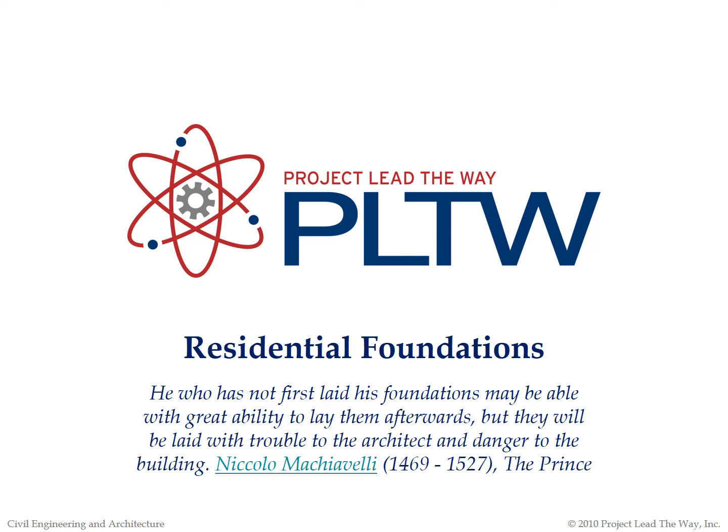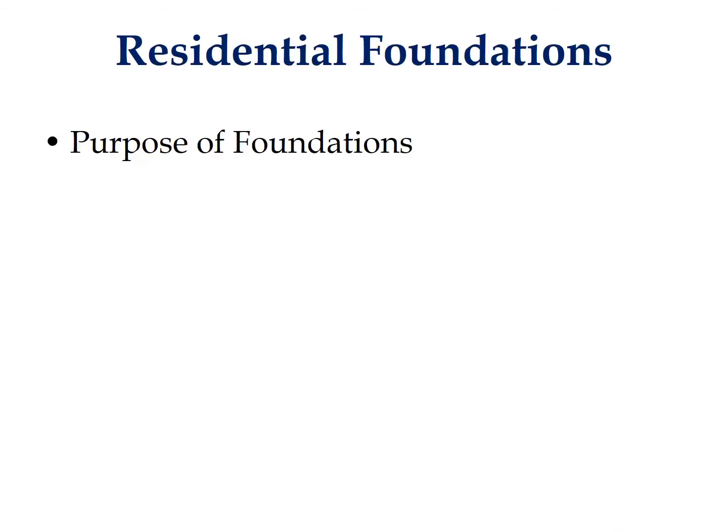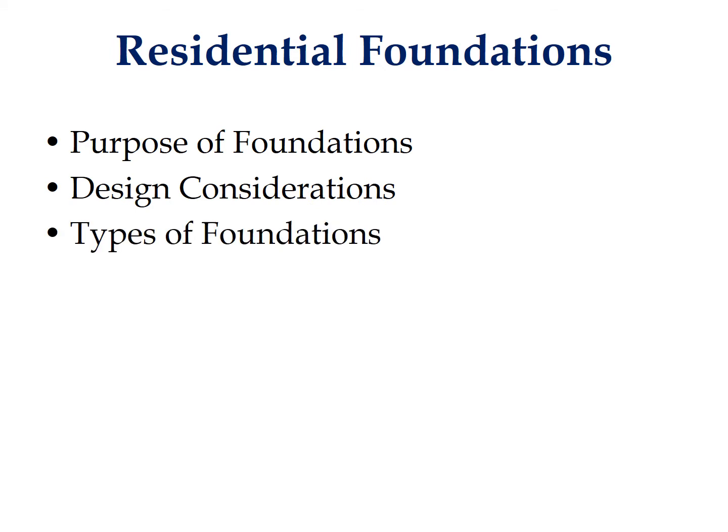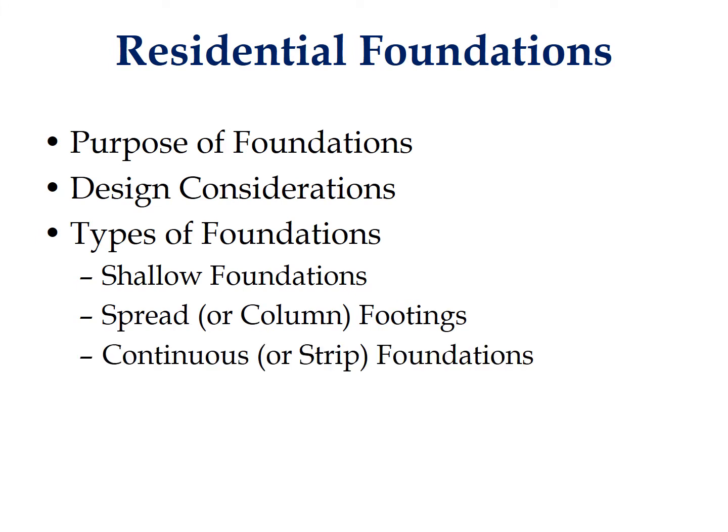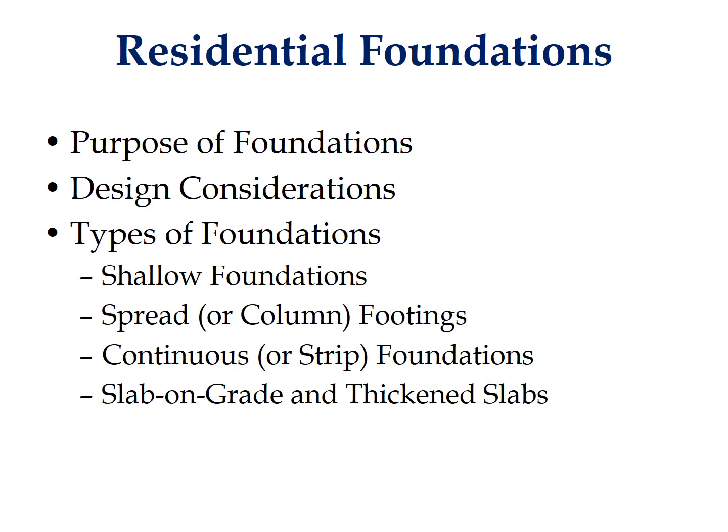In this presentation, we will talk about residential foundations. We're going to talk about the purpose of foundations, the design considerations, and types of foundations. And the types of foundations we're going to cover in this presentation are shallow foundations, spread or column footings, continuous or strip foundations, and slab-on-grade and thickened slabs.